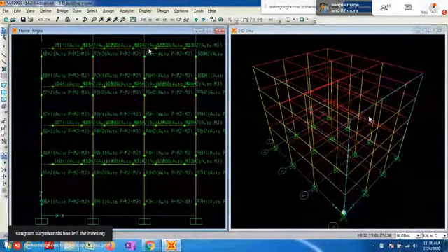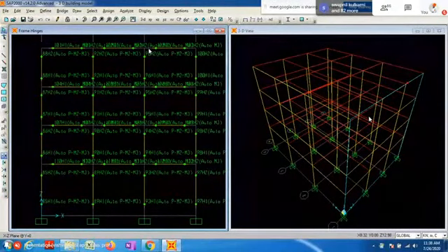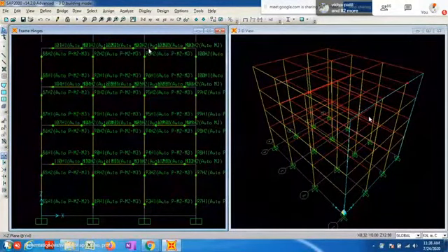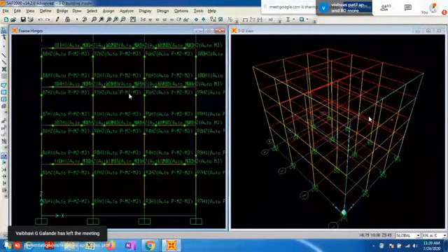Okay, so that is it, but in this case, if the shear wall is not provided, that also works less. Then what about the slab? Now the slab, we have modified it as a rigid diaphragm, so the slab is not going to fail, it is just moving in the horizontal x and y direction. So this is a complete non-linearity. When you are confirmed that it is a complete non-linearity, then go for the analysis.